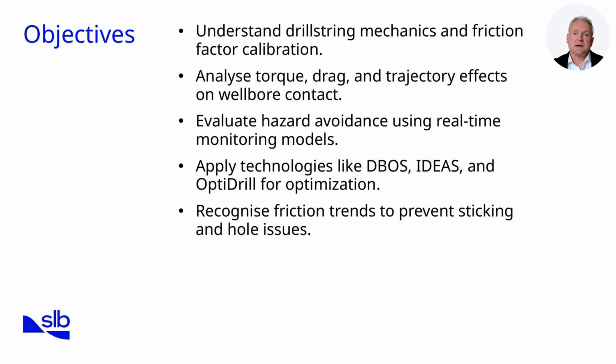Finally, we set out to recognize friction factor trends. This was addressed through the exercise interpreting pickup, slack-off, and rotating weights to identify issues such as poor hole cleaning or differential sticking. By the end of this session, you'll understand how drill string monitoring drives safe, efficient drilling.